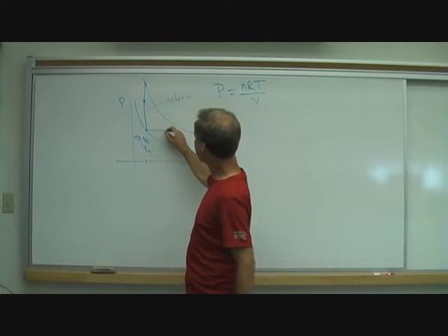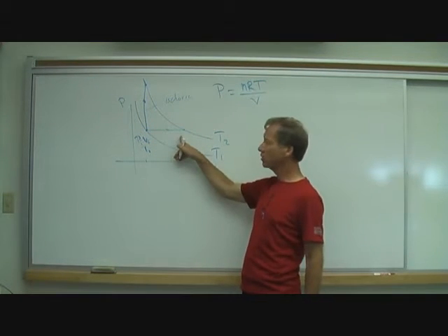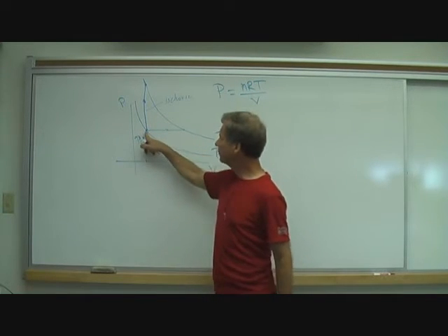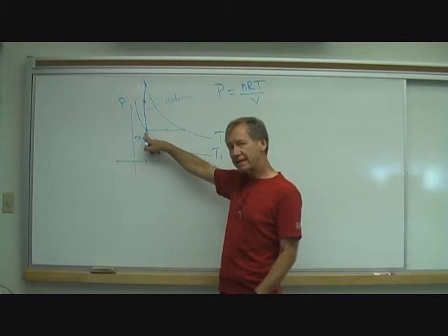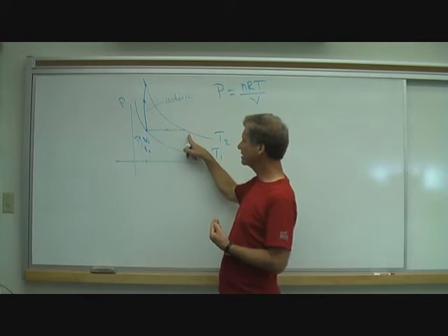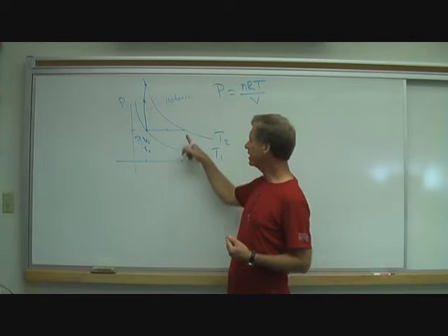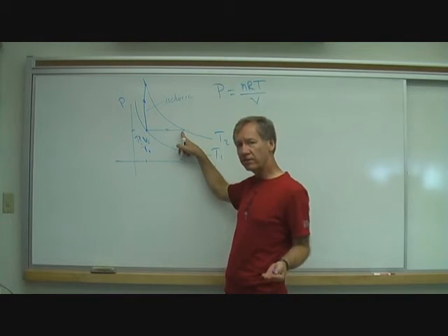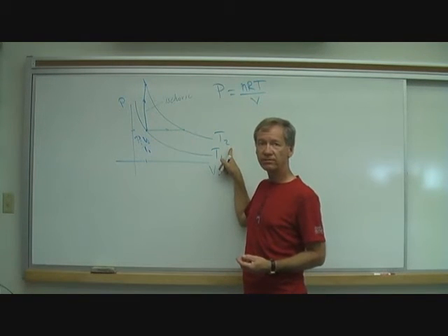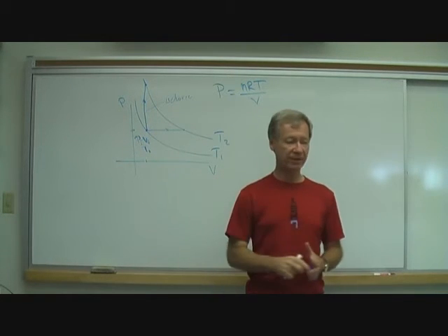Here is the isobaric process. That would take us from our initial to our final state. Again, we know that if we start here, we supply heat, we increase the temperature, doing a process that is a constant pressure process. Then here is where the new volume value will be at this new temperature. So diagrammatically, this is what's happening for us.